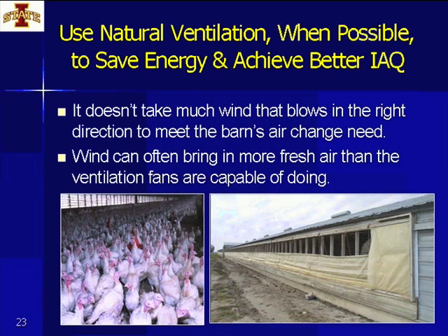Whenever the conditions permit, we should consider natural ventilation to save energy. And a lot of time, we achieve better indoor air quality. It really doesn't take a whole lot of wind, if it comes in the right direction, to achieve the barn's air change need.